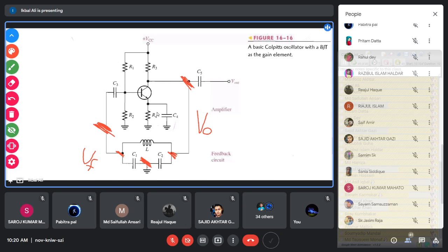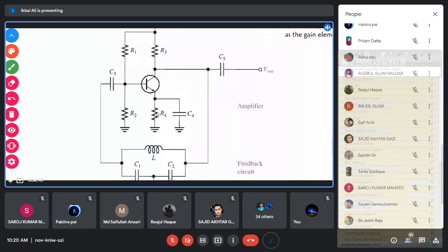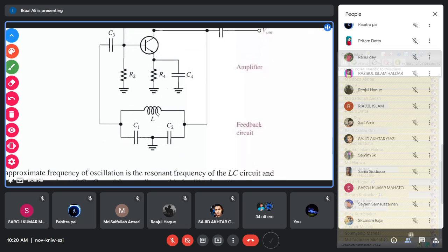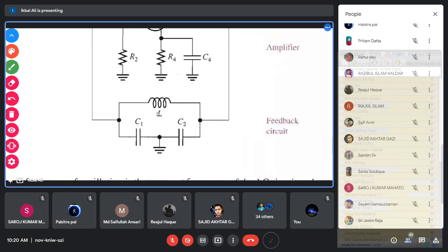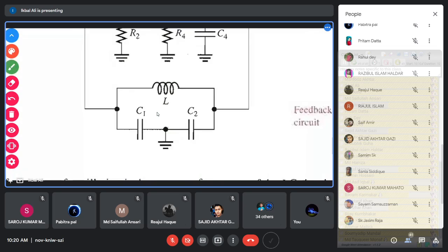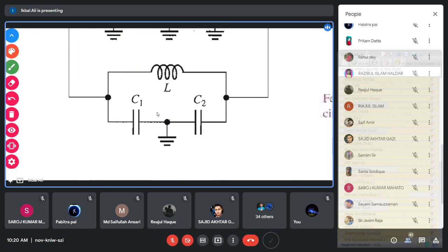And also we have analyzed this circuit a little bit. How to analyze this circuit? We analyzed this tank circuit only, as we did last day, just to show you how we analyzed it. We took a current into the feedback loop. That means that within this beta network, we have taken a current like this.